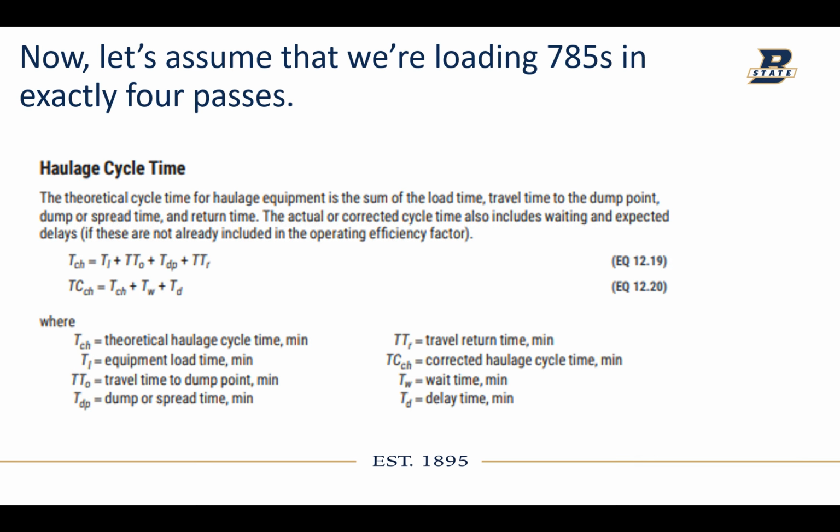So how long does it take? How many trucks do we need? And to figure that out, we have to take into account the haulage cycle time. That theoretical cycle time is how long it takes to load the equipment, plus the travel time to the dump point, so the loaded travel time, the dump time, like how long it takes to dump, and then you have the return time, which is unloaded and probably a bit faster. Then a corrected haulage cycle time, which is then equal to that, taking into account the wait time and the delay time.